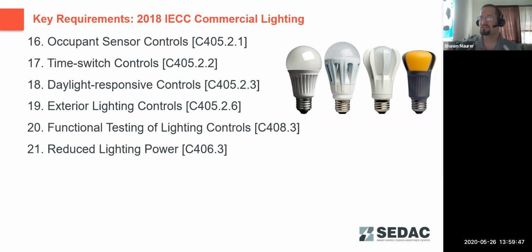Then we got another question. Does mechanical section C403 apply to direct replacement like-for-like equipment? For example, a rooftop unit on an existing building that's being replaced. To our understanding from what we read, that falls under the alteration section in C503, I believe. Where you would have to do a sizing calculation to properly match that new unit to the building's loads. So C403 would apply there.